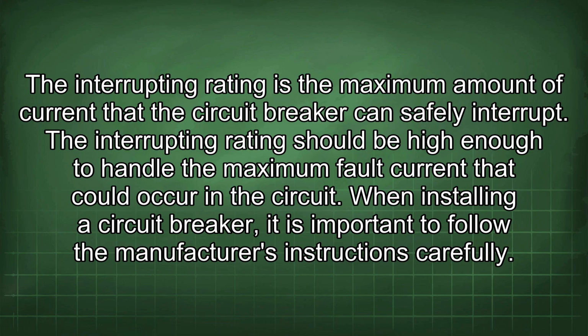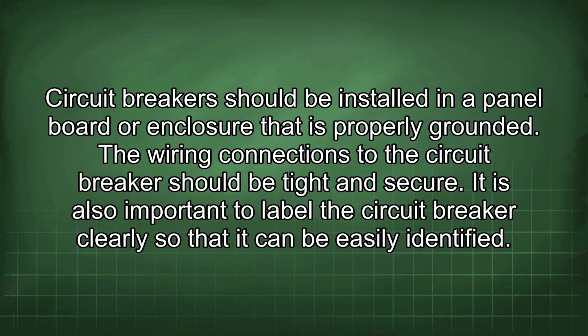When installing a circuit breaker, it is important to follow the manufacturer's instructions carefully. Circuit breakers should be installed in a panel board or enclosure that is properly grounded. The wiring connections to the circuit breaker should be tight and secure.